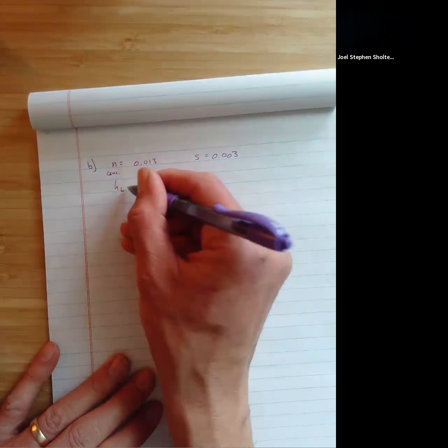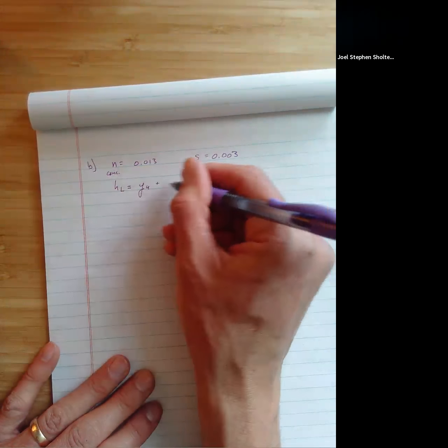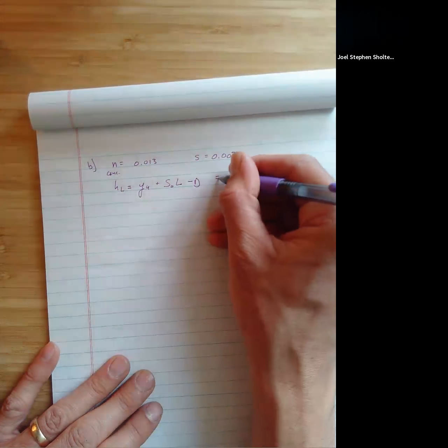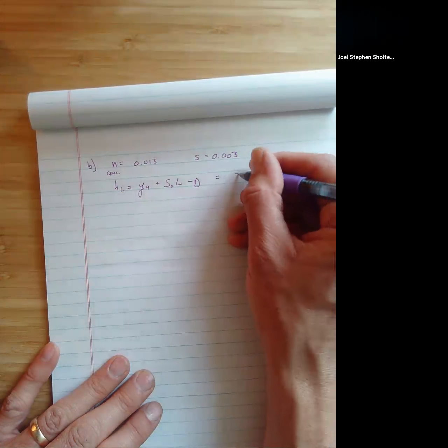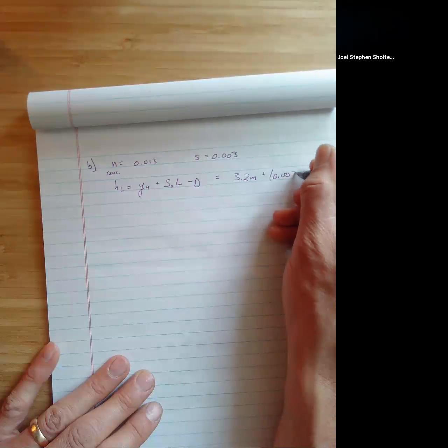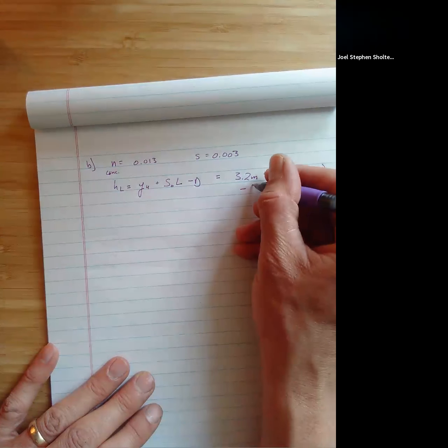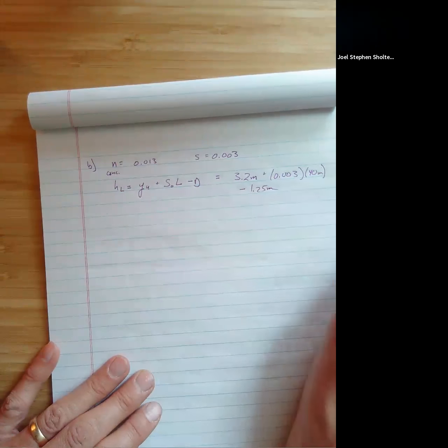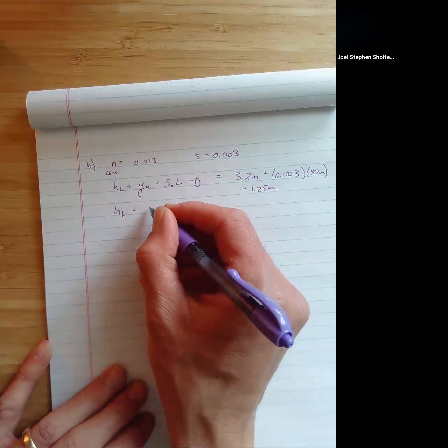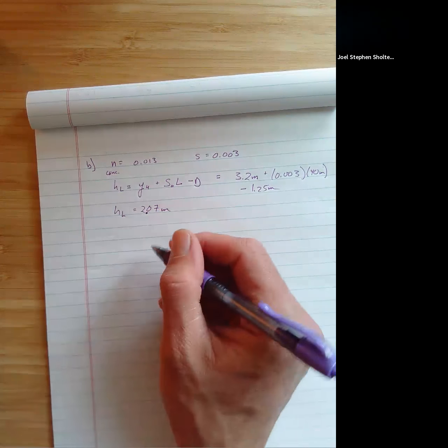So head loss is equal to the upper depth plus the slope times the length minus the diameter. Okay, so that depth we said from upstream was 3.2 meters. That slope, and then minus 1.25. So we're going to say, can we use this diameter of 1.25 meters? All right. So in this case, the head loss is equal to 2.07. Okay, so now we calculate the actual head loss and compare.